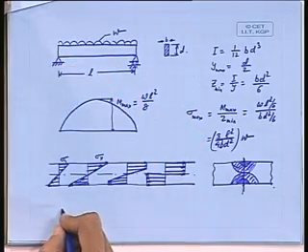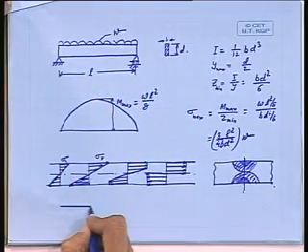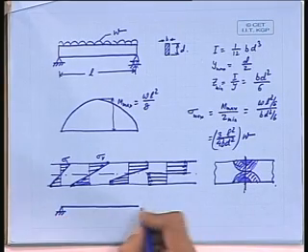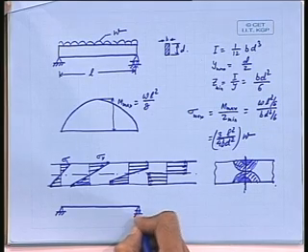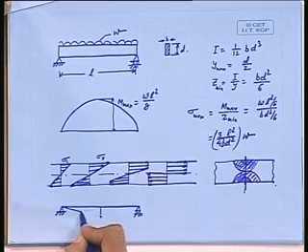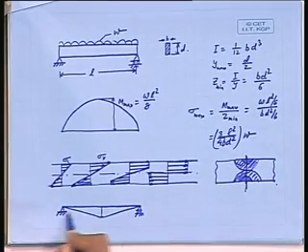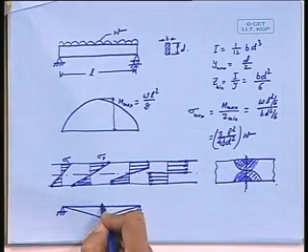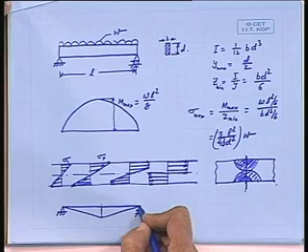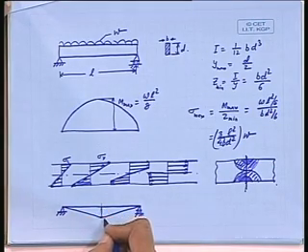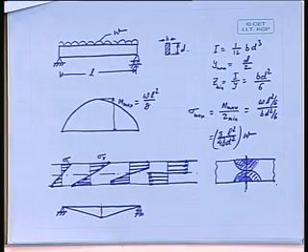So if I draw a line here, a line representation of this particular diagram, then at this point it will simply go down under the effect of all this, because these regions are still elastic, acting like a rod, and this section has become fully plastic, and you have two usual supports which are hinges, and this will also act like a hinge, and if you are supporting it with 3 hinges, this is likely to collapse.